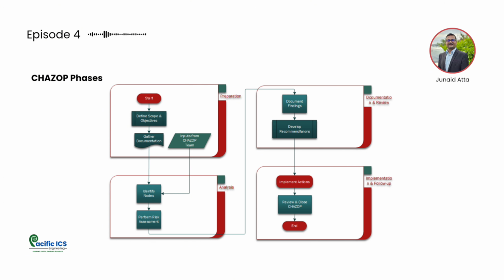Also, we can identify the key concerns and expected outcomes. In this phase, we gather all the necessary documentation like P&IDs, functional descriptions, and failure records. We also gather the team, which includes control engineers, safety personnel, IT experts, and operators, as well as a cybersecurity engineer as and when required.